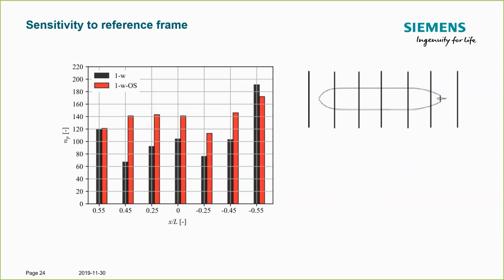And then you can see as we approach the midship area, which is the most important one for the contact forces, you can see that in the overset or the moving ship method, there is a substantially higher particle count, which is attributable to the higher disturbance velocity. The particles were disrupted by the presence of the ship a lot more than in the upstream injector approach, because the downstream drift is more dominant.